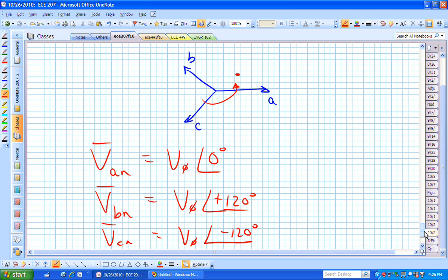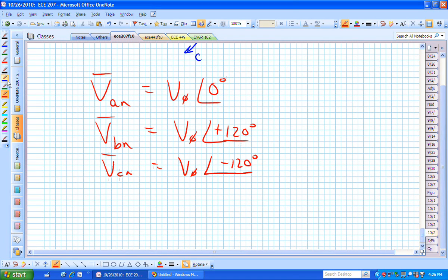They may just have their machines interconnected in such a way that what they've labeled the A phase, the C phase, and the B phase, it's circulating as ACB, ACB. But you know how to analyze it. You analyze it just the same, except you just have to keep track of this relationship between the B and the C phase relative to the A phase. Not a big deal. Another modification, this one's a little bit more interesting.